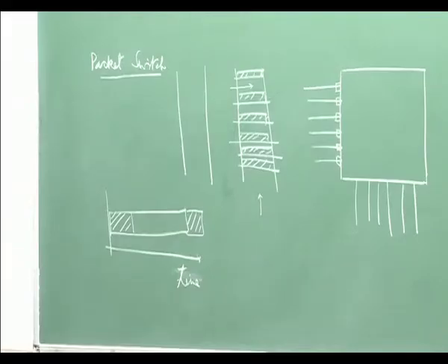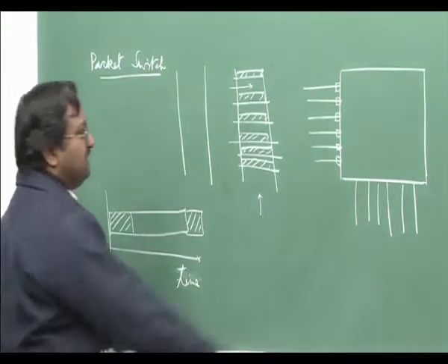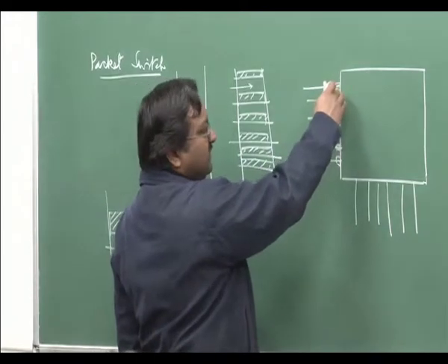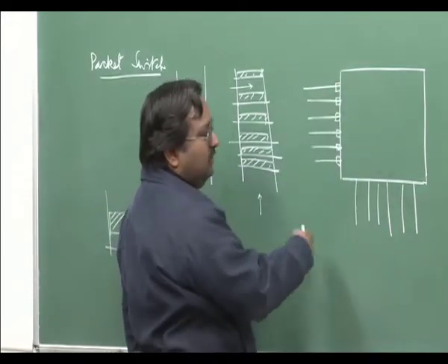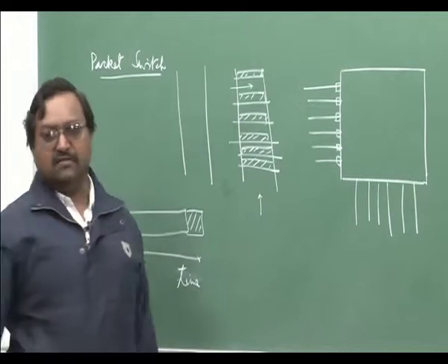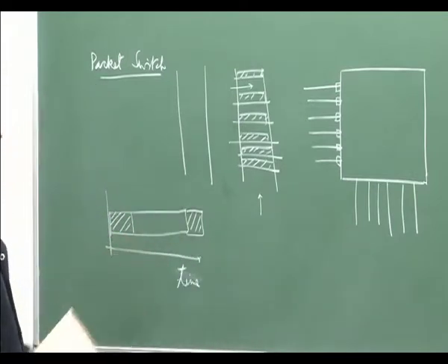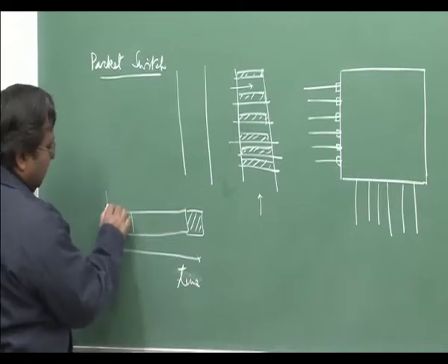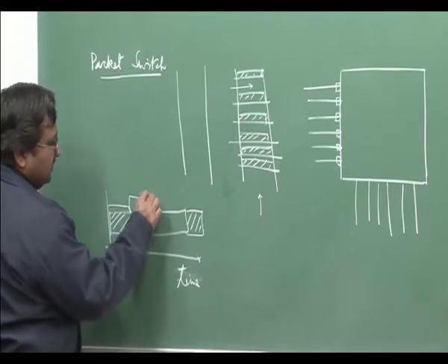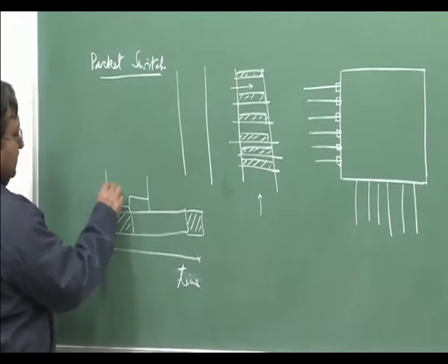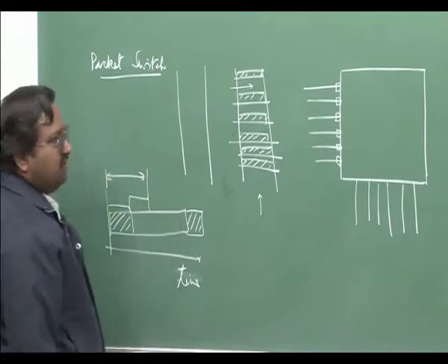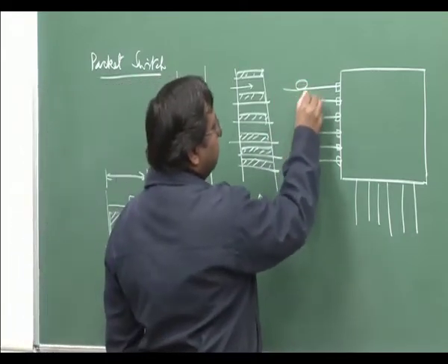There is a possibility of even doing CRC checking, but then the whole packet has to be received first, here CRC has to be verified, and then only the routing will happen. So, there is going to be one slot delay which will happen at the interface board in that case. Usually delay will be for reading of only the header part, and then there is some processing time, worst case processing time, this much delay will be required. So, we have to introduce that delay here.